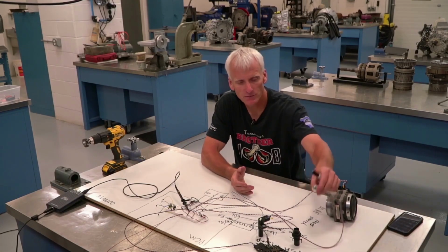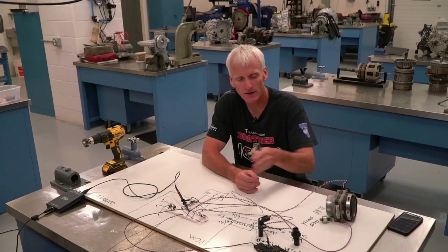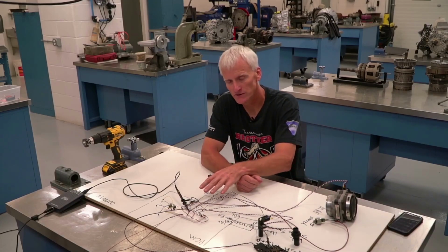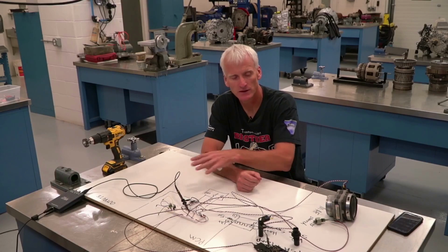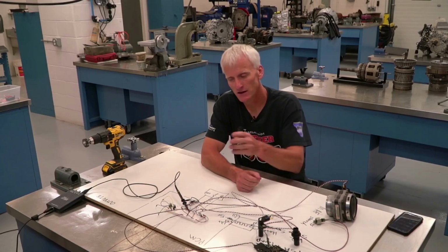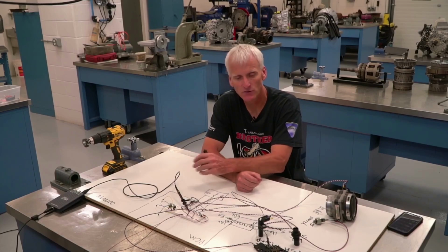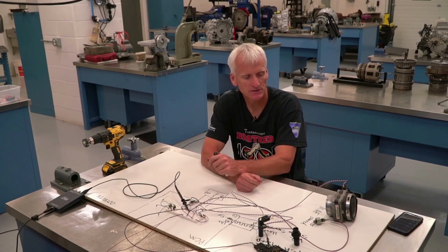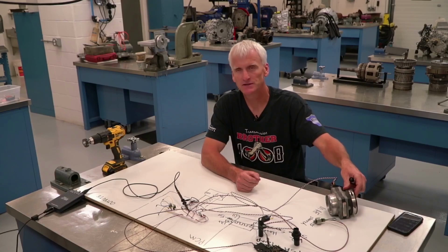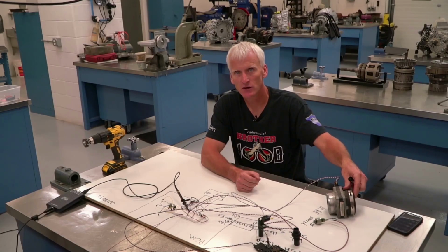We also have pressure sensors. Those are important feedback. If the computer is wanting to know if it's controlling the pressure in the transmission properly, it's going to look at this sensor to say, okay, do my actual and desired pressures match? If not, then it's going to have to tweak the pressure control side of things. And then we have sensors like this mass airflow sensor that provides information on load.